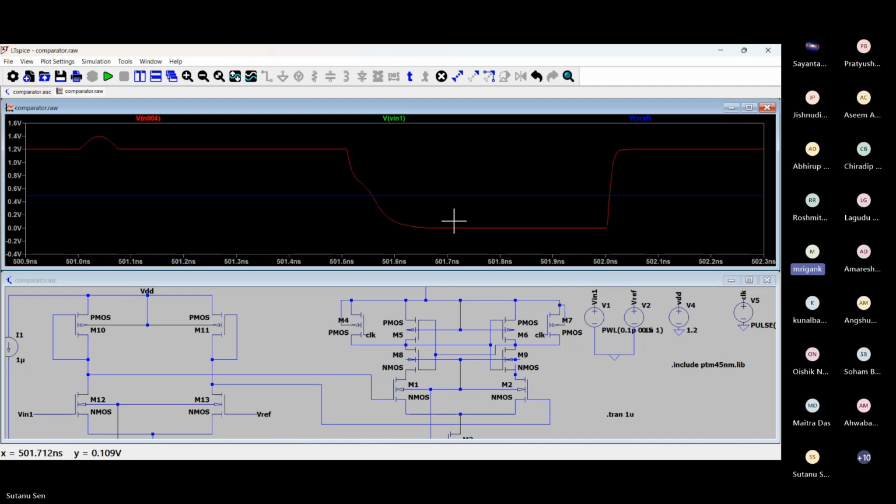what is the problem? For the preamplifier, we are able to get the high frequency small signal model. What is the problem with the second stage? It is not operating in small signal mode, right? It is completely operating in large signal, latching, going to VDD or ground. It is a discrete time signal. It is not a continuous time circuit.